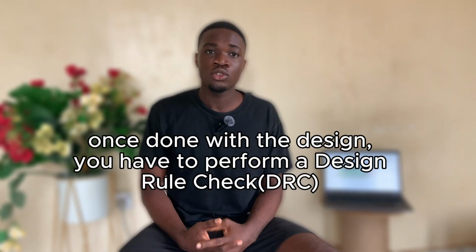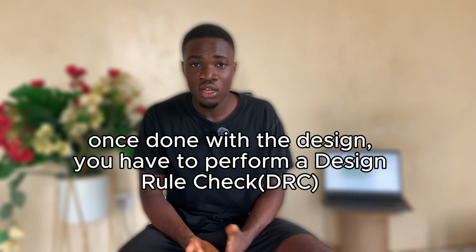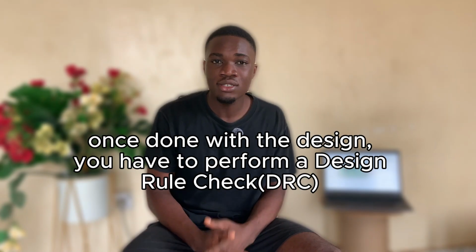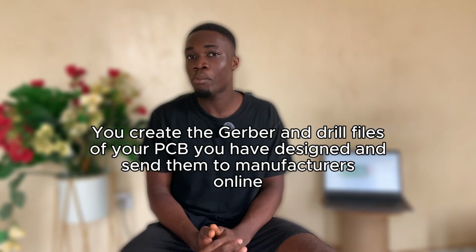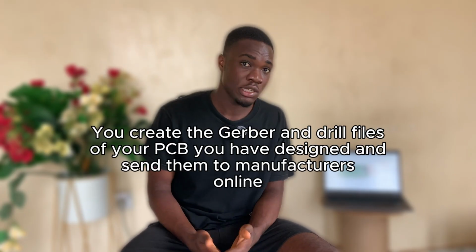On everything, you can do your design rule check to confirm if your board obeys every manufacturing capability. After that, you can give your board to a suitable manufacturer like JLCPCB for instance, or PCBWay, NextPCB to manufacture your board for you. Or you can do it yourself, like I said earlier, which is a limited approach and impractical. And I don't think you can do it for complex layer boards.